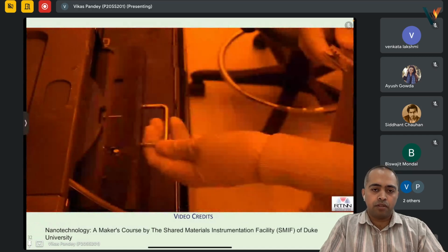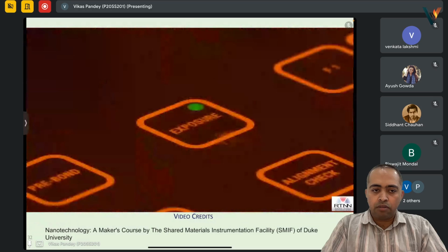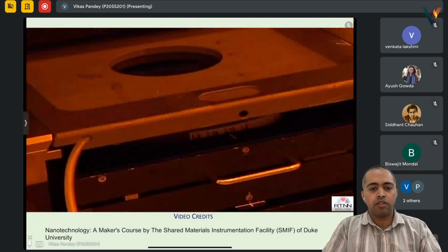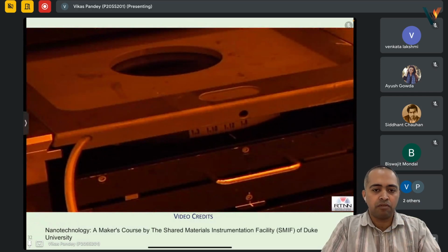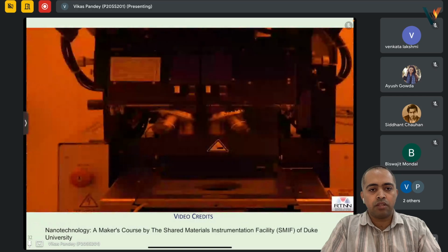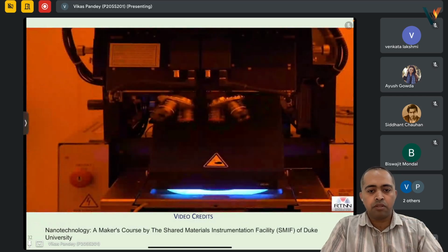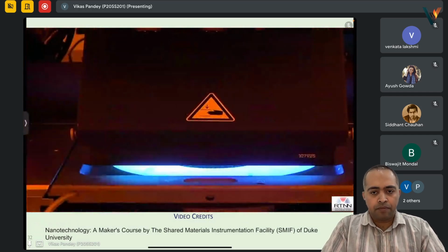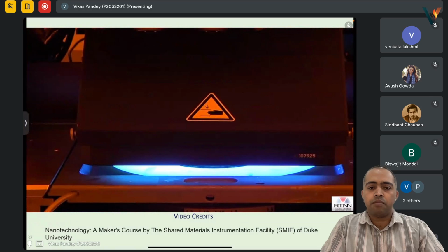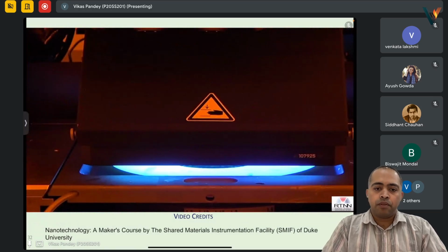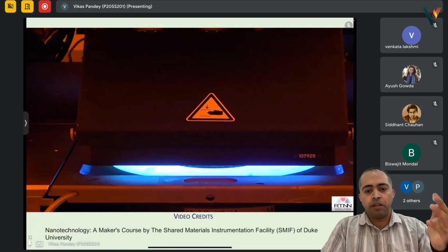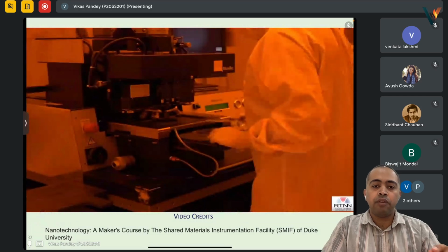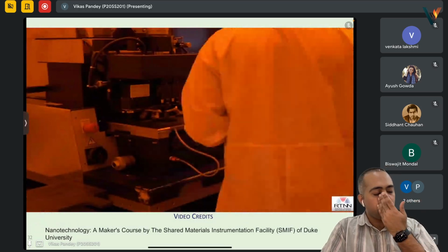Since this UV light we cannot see directly, this whole process is done in a closed surface. You can see just some bluish colored reflection. The whole setup exposes. Once this exposure is done, it will not be infinite. It will be fixed for a time, since that will again depend on the thickness and the type of photoresist we are using.